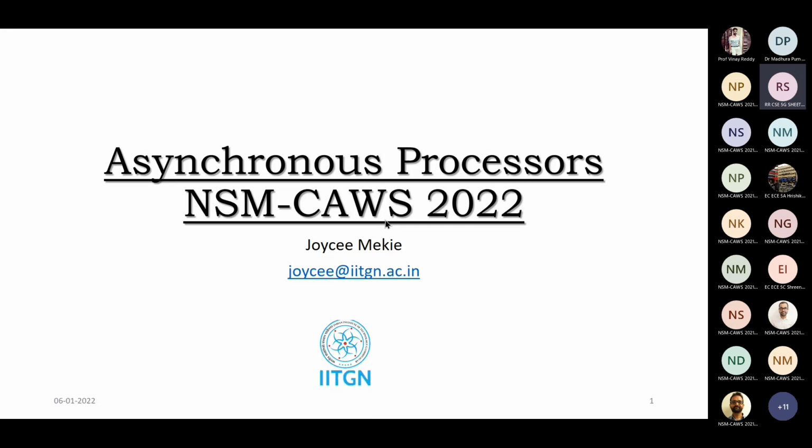So the easiest place where we can think of asynchronicity coming into chips is when we talk about multiple clock domains, right? Multi-clock domains, as it is called. Many SOCs today are multi-clock domains, and each clock domain internally has its own clock distribution tree, which is local to that particular IP on the SOC.